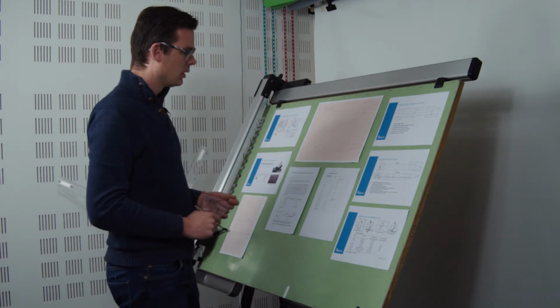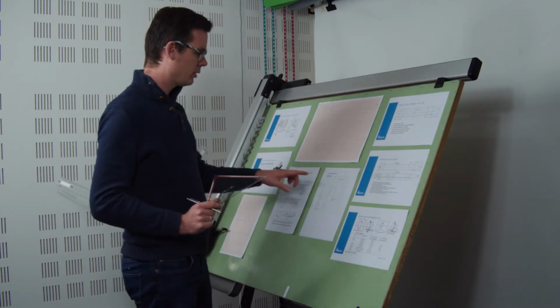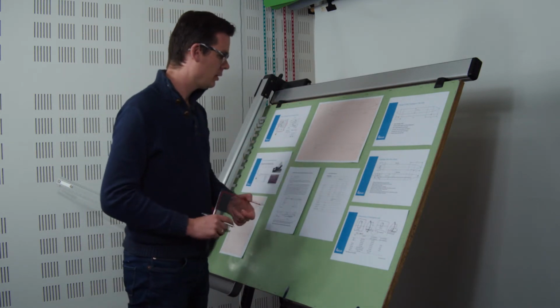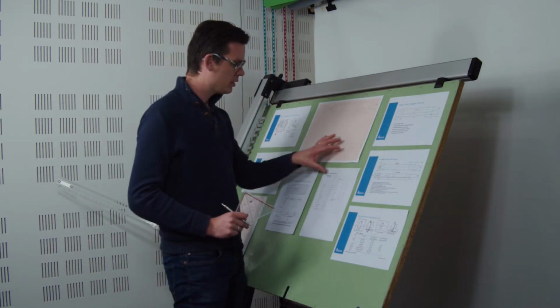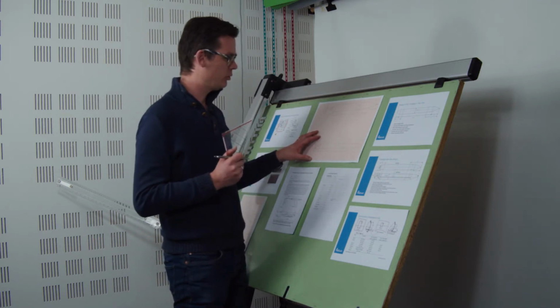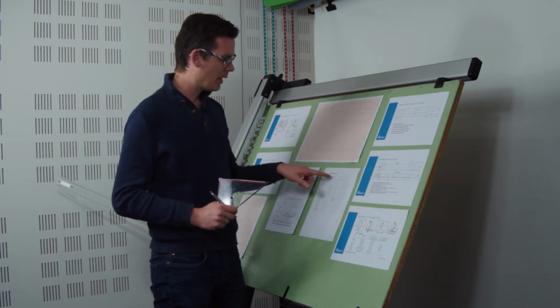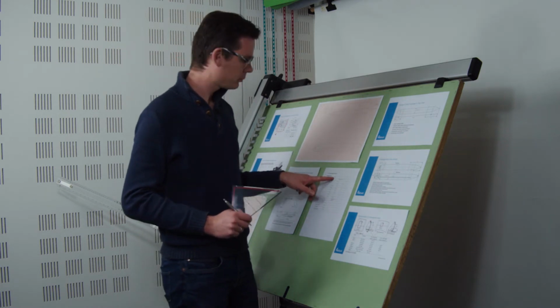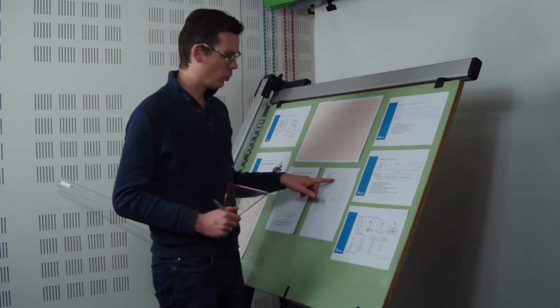Now the next step that we need to do is to draw in the emergency exits. So the first thing to know is how many do we need, and then I look at the number of passengers that are in this design, and it's 105. 105 passengers in this barrel, but I'm thinking a little bit ahead, and I want to sell this airplane maybe to different operators, and maybe I have designed it for 105 passengers, but maybe there's an operator that wants to reduce the seat pitch a little bit and add another row, or maybe even two.